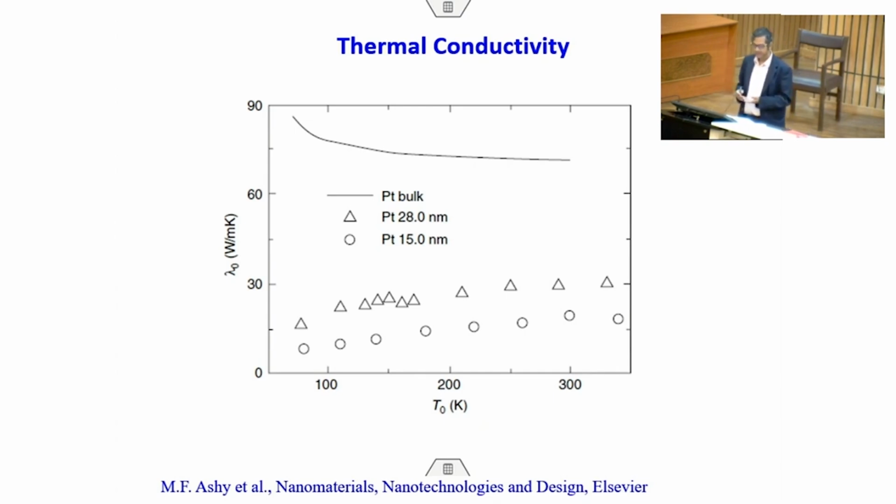These nanostructure thin film materials can be subdivided into nanocrystalline materials or nanoporous materials. So in multi-layer thin films, each layer's grain structure can be nanoscale or micron scale, both are possible. Since each layer is of nanometric thickness, it is a nanomaterial. You can also have nanometric pores in the layers. So you have these 3 or 4 different types of situations.